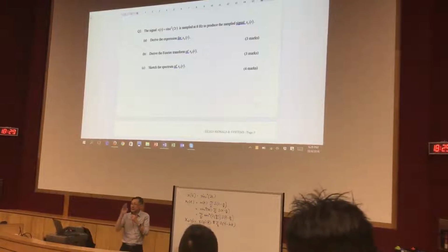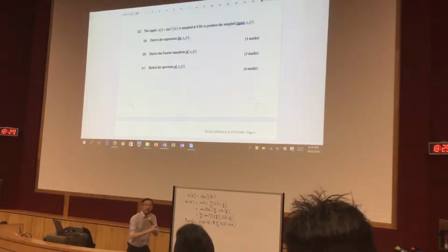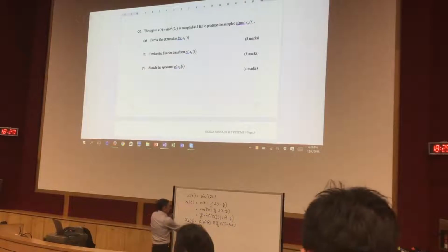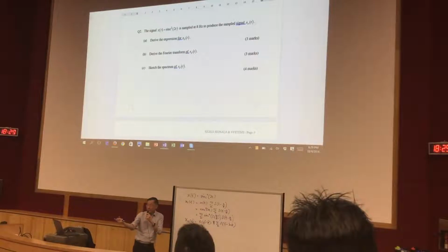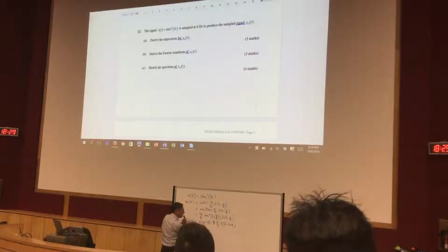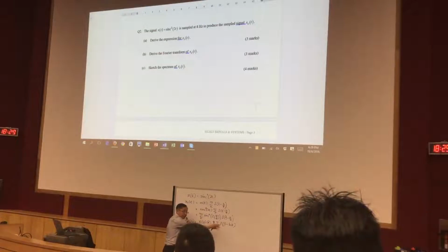Yeah, at 8 Hz, at 16 Hz, at 24 Hz, etc. Okay? What is X(f)? Sinc squared if you try. Correct? So the tri will go here, and you convolve it, it becomes periodic here.